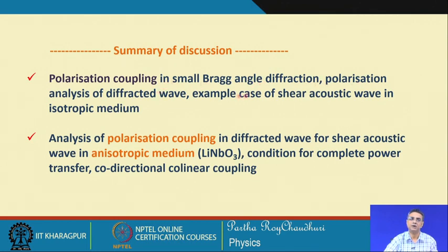We considered the polarization coupling analysis for the diffracted wave, and took up the example of the shear acoustic wave in an isotropic medium. Then we considered the example of a shear acoustic wave propagating in lithium niobate, which is an anisotropic medium. Then we considered the condition for complete transfer of power.